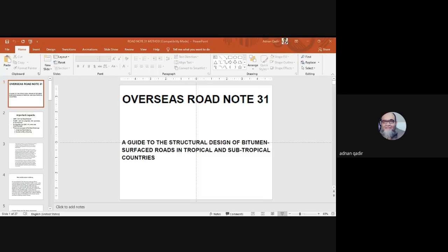And then there are two types of surface dressing: single surface dressing and double surface dressing. That's why I say this is the best method for designing a shoulder, because our shoulders are normally SSD shoulders or DSD shoulders. Single surface dressings are normally adequate when applied to a bituminous layer. To be satisfactory on non-bituminous surfacing, the quality of the single seal must be very high, and subsequent minor maintenance must be carried out promptly when required. It is recommended that double surface dressings are always used on non-bituminous layers.